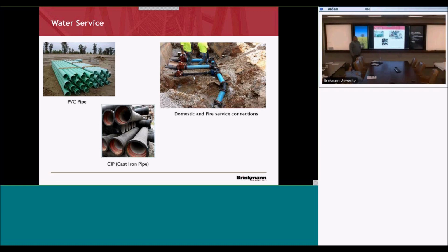Also on water meters, I've had it on my last 2 projects here in St. Louis with MSD, where I have a water meter for my building, domestic water, and then I have an irrigation water meter as well. So you could have 2 of those meters and 2 backflow preventers on those as well. And that is so they can determine how much water is going down the storm drain. Because typically if you just have 1 meter, whatever goes through that meter, the municipality looks at as what's going down their storm drain or their sewer, right?